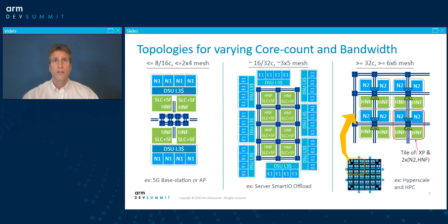For small configuration examples, let's say on the right-hand side, we advise placing the CPU clusters and system cache outside the mesh fabric. That mesh fabric is the small 8 boxes in the middle. The 4 system caches in the green and the 2 CPUs and the DynamIQ Shared Unit L3 clusters of N1s are on the bookends, top and bottom. This allows for very short inter-cross-point signal channels in between those cross points to minimize the area due to the fabric.